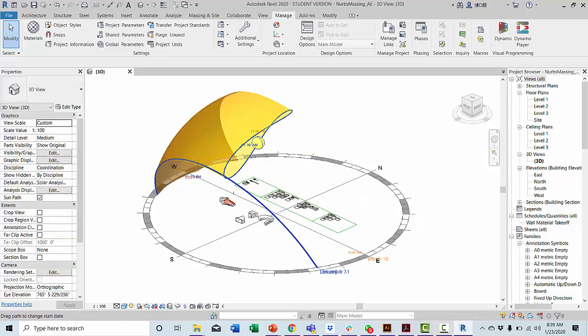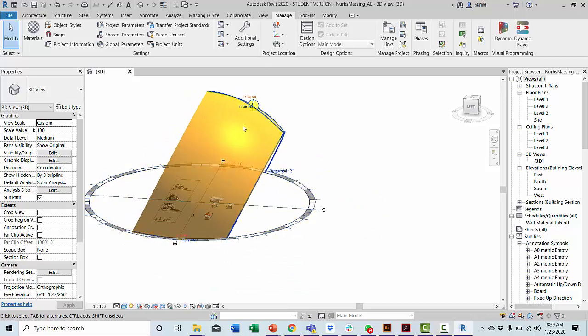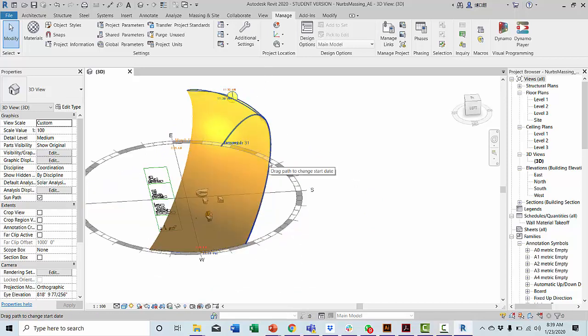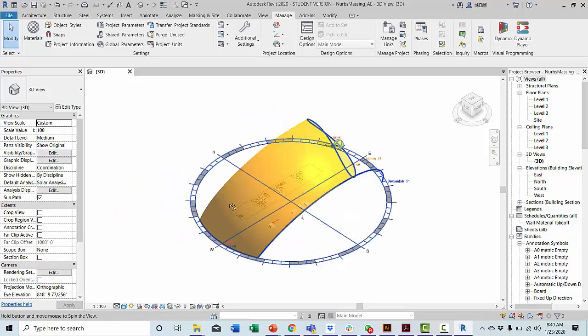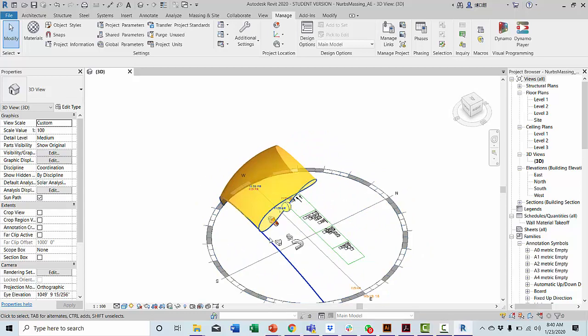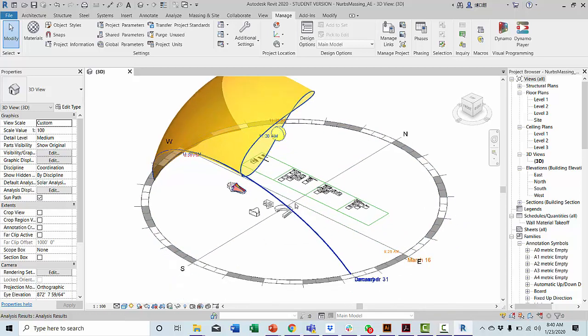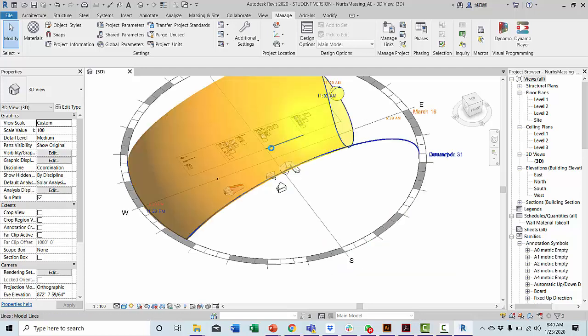This is something that you can take into consideration too. If you see all the year, the sun is more south than north. That means the south is the one that is going to get more affected. In the southern hemisphere it would be the opposite. So in winter the sun is at lower angles, and in summer the sun is higher. If I move it here, I'm basically moving the time of the day, and if I move it here, I'm basically moving the day of the analysis.